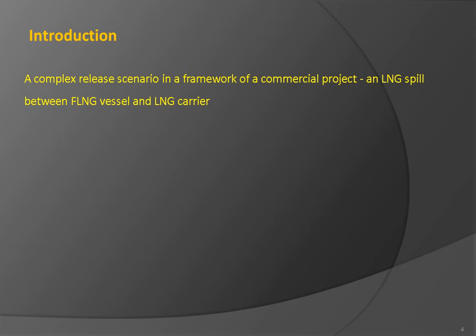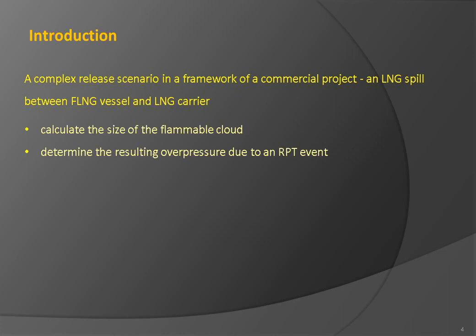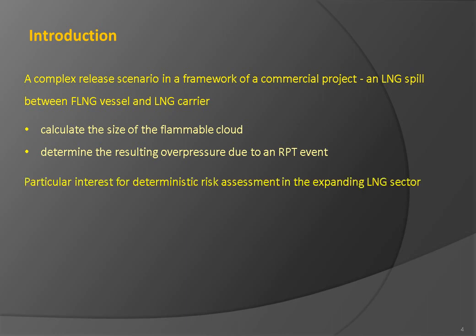The project focused on the behavior of an energy spill between a floating LNG vessel and an LNG carrier in order to calculate the size of the flammable cloud and to determine the resulting overpressure due to an RPT event. These topics are of particular interest to deterministic risk assessment in the expanding LNG sector.